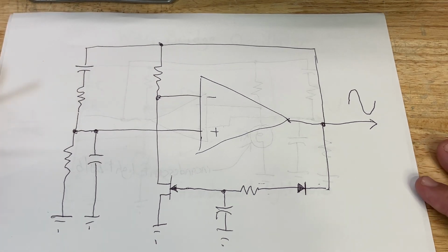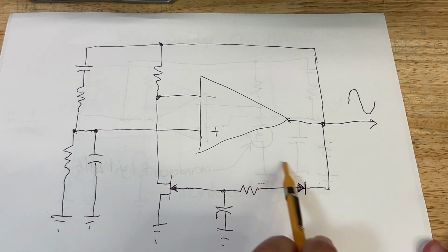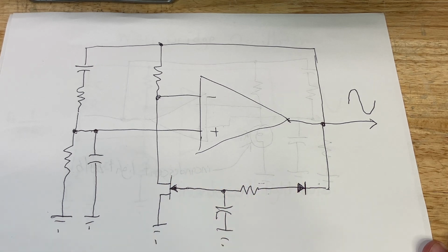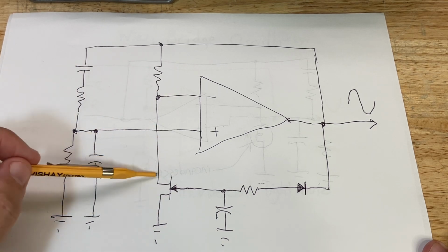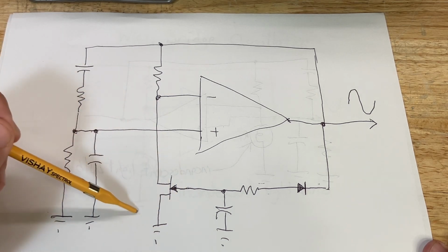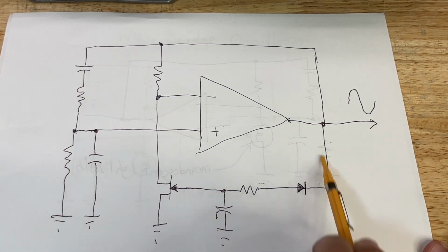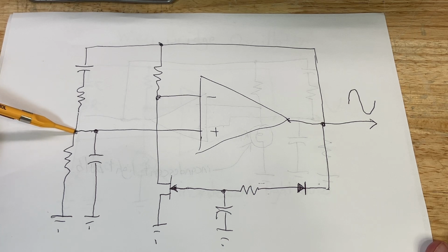So the 204C solid state oscillator does not use a light bulb. It uses this more complicated feedback circuit, and there's some other additional circuitry in here, buffers and so on, and voltage level shifters to make the FET bias properly. But essentially, it's the same basic circuit, except they have replaced the light bulb with a FET and some control circuitry to drive that. So this is the Wien bridge type oscillator circuit in the 204C.